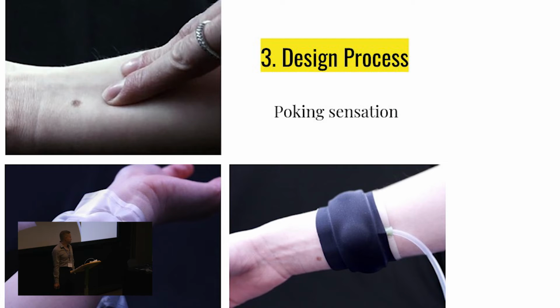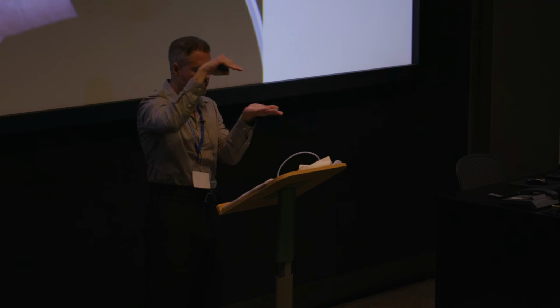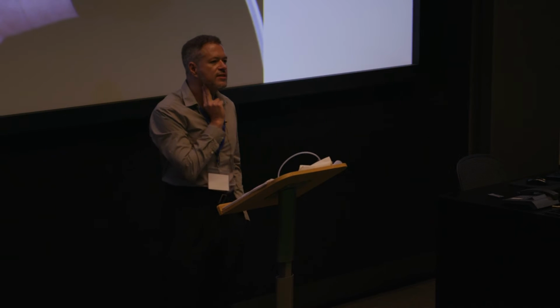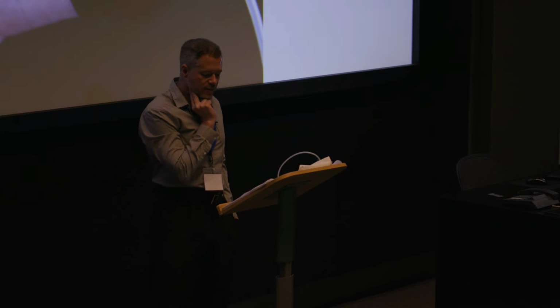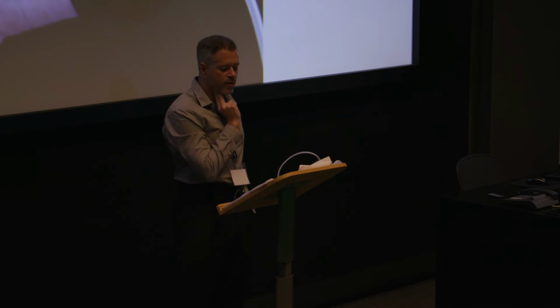Now I will share the process of crafting the sensations. We start with the poking. For this poking sensation, we selected a circular geometry because it deforms upwards when actuated. It's sort of a bubble that goes up when you put air in, creating pressure at one point, similar to the sensation of poking. We started with the heat sealing technique and used the silicone ball technique for comparison.